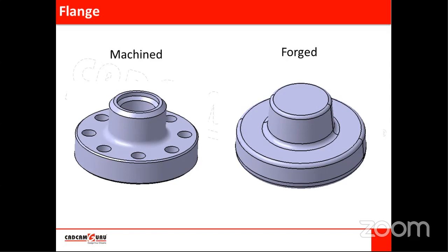So they had to create their die drawing, and using that drawing they would manufacture dies. They would do the first forging with that die, send the component for approval. If approved, go ahead with the same die. Otherwise, if there is a problem, they have to change the dimensions of the dies and remanufacture it. That cycle had to be repeated a number of times.